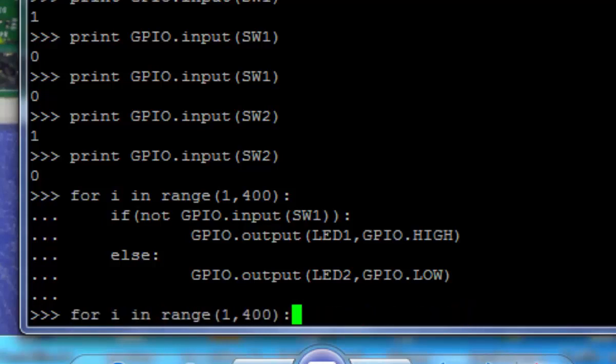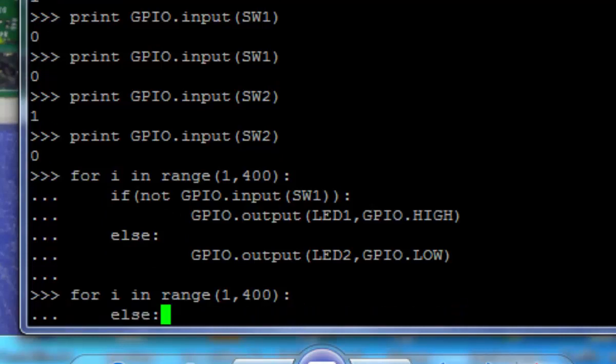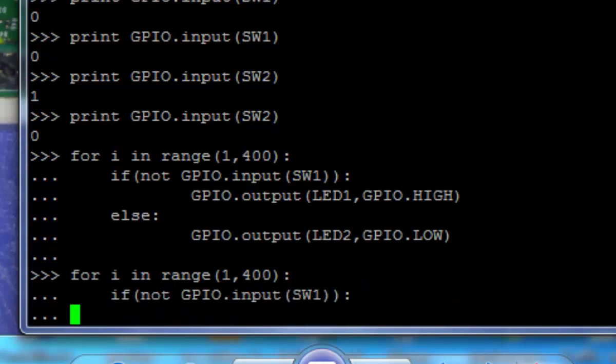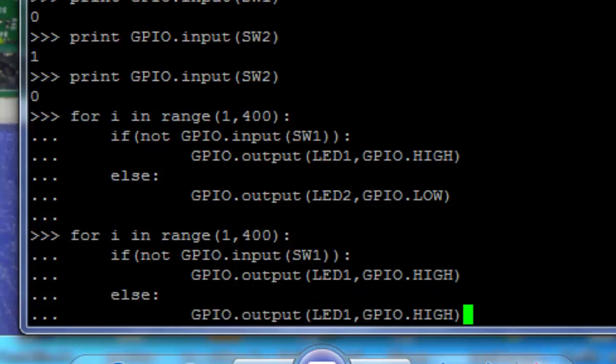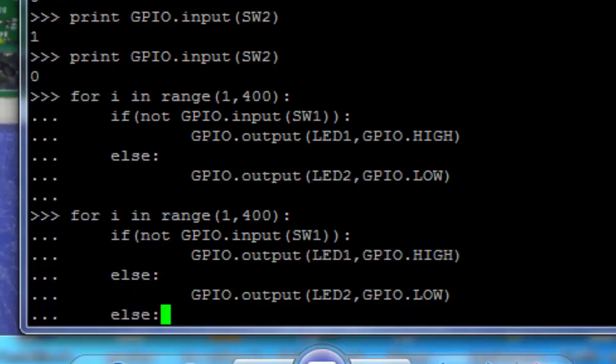So the last thing that we need to do if we want to implement this logic is to slow down the process. And for slowing down this process we need to add some delay in it. So for adding some delay, we had already imported our library for creating the delay, which is the time library. So what we are going to do here is just to give a smaller delay which will not interfere in detecting our switches. So this delay will be almost 2 milliseconds.